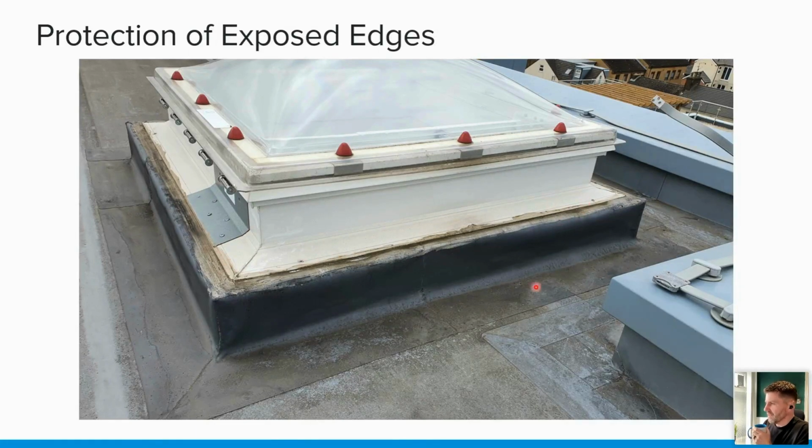But anyway, the important thing here is that the mechanical fixings, of course, should be adequate, but they should be taking the waterproofing up to finish underneath this protected lip here, because this mastic seal is just going to fail over time, and then water is eventually going to get ingress into here. So the membrane should be finished underneath here, and protected by this preformed kind of flashing that's on the roof light.